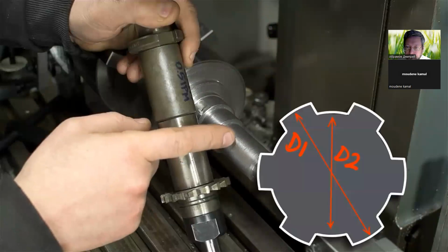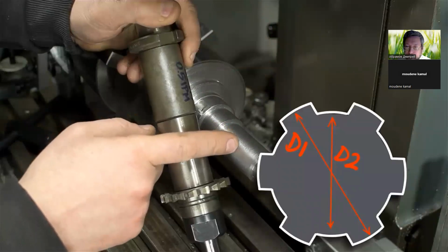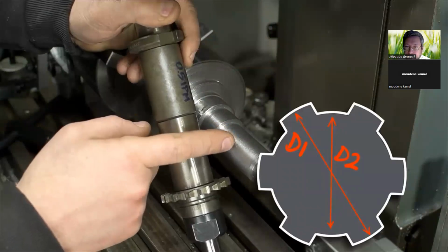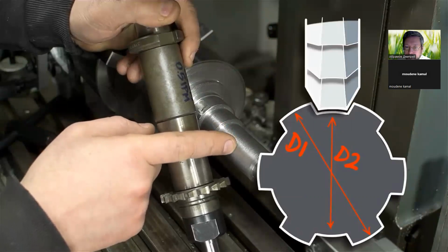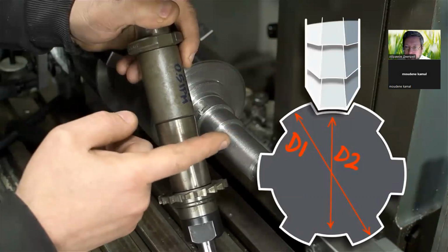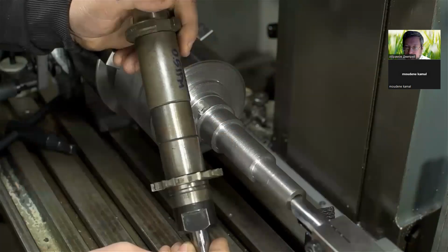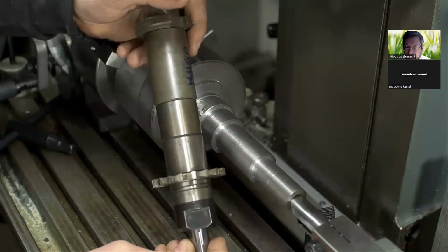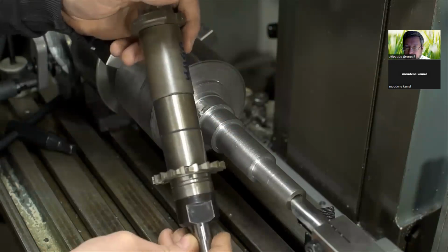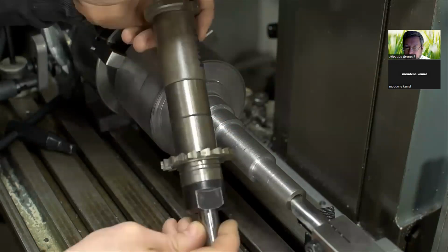These splines have a minor diameter. That means in between the splines, it's round. And technically, I would need a form cutter of the right size to do this. Something that in one pass would leave a finished spline profile. This cutter is going to leave that minor diameter a bit faceted, I guess, depending how much I approximate it. Hopefully that'll make more sense as I work through this, if this works at all.